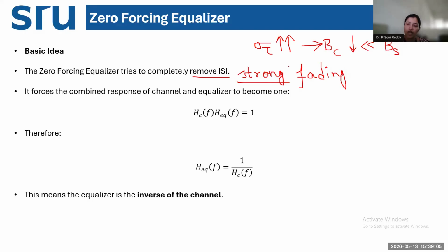At the receiver, you will have multiple copies of the same transmitted signal, which are delayed versions of the transmitted signal. Due to this delay, some components will have a difference in amplitude and some a difference in phase, and when you sum them all, you get what is called destructive interference.